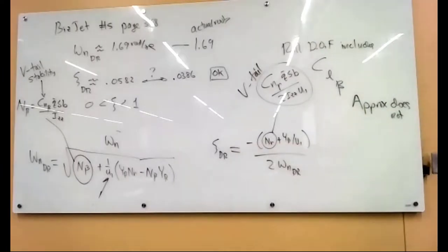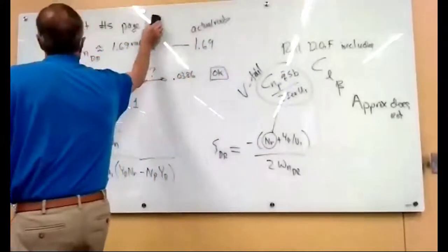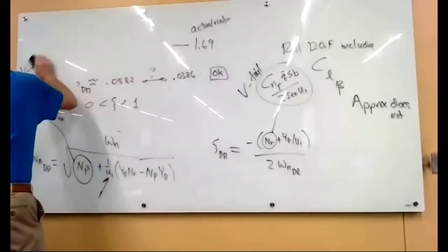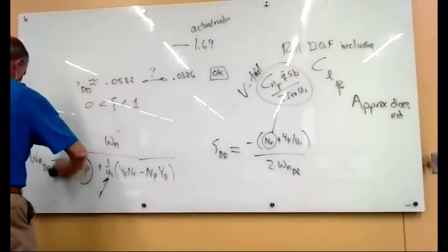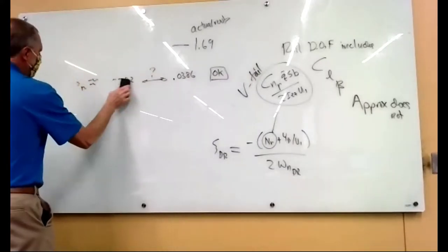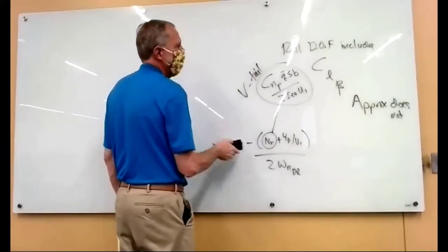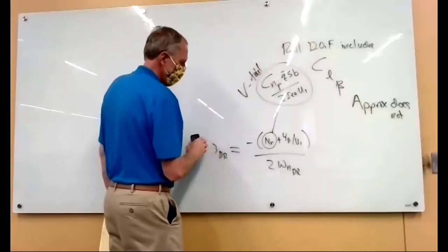So these approximations, again, are design tools where you get a lot better clue as to what's dominating or what's important inside these different modes. Okay, so that's a Dutch roll. The roll mode can be approximated really easily. Because it's just a pure rolling motion. And so all we do is take the roll equation, the one we knocked out to get this one, we just use that one.